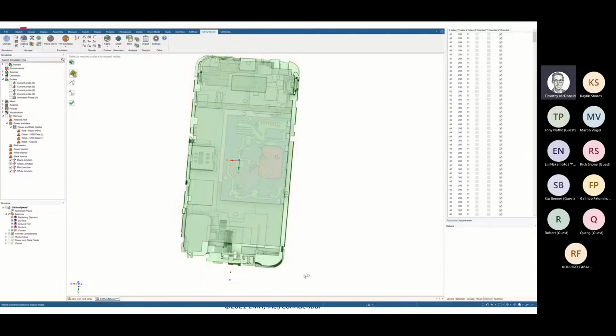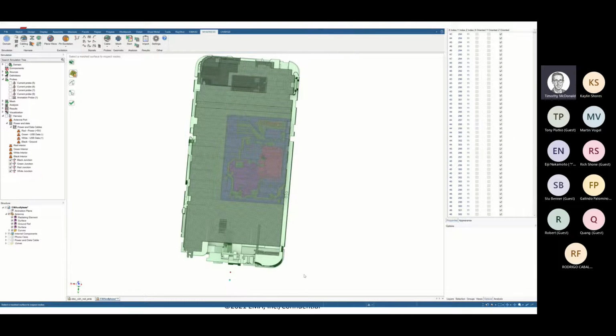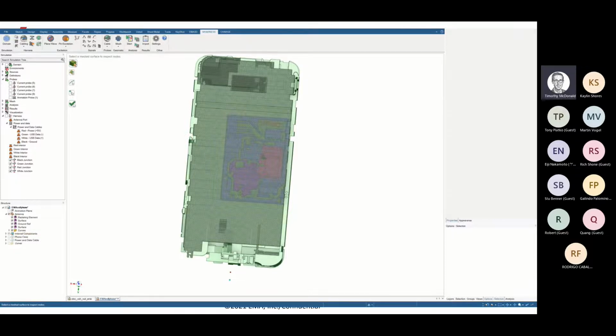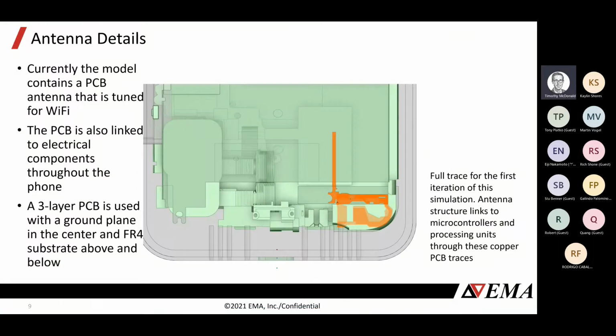solving across something that creates tiny, tiny voxels. So voxels, think like Minecraft. They're tiny boxes. And so by using those tiny boxes, we can dramatically reduce the time it takes to build and analyze our models. So we take a look at the Wi-Fi antenna. What we want to answer in this particular example is, what is the coupling between this antenna and the power cable, the USB cable that I use on this phone?